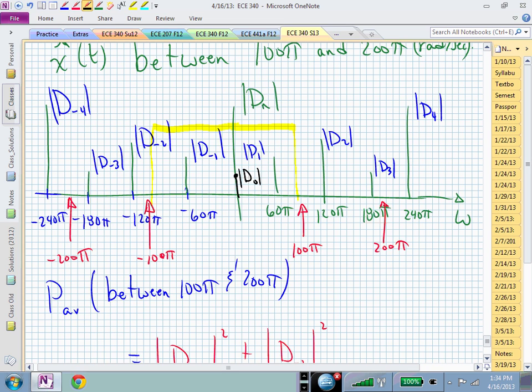Wouldn't the DC part actually have a 1/2? The others have like a 1/2. That part is clear. So now whatever you ended up computing for d sub 0, however you define that, if that was now in terms of some a sub zeros, there's already a built-in factor of 2 built into d sub 0. So to get its power, all you do is square it. That's all we did in our formula. So all of those factors of 2 are accounted for if we've computed the d's properly.